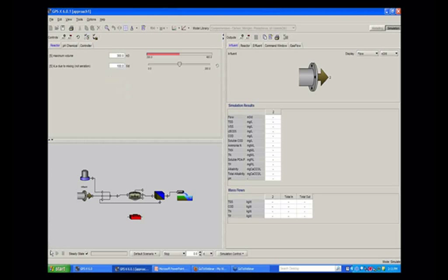So I'm just going to run with the default settings, and I'm going to just run a steady state simulation, and you can see that the model converges, and we can see the flow rate which is going into the digester object is 2400 meter cube per day with a TSS concentration of 108 and total BOD of 1500 going into the reactor.